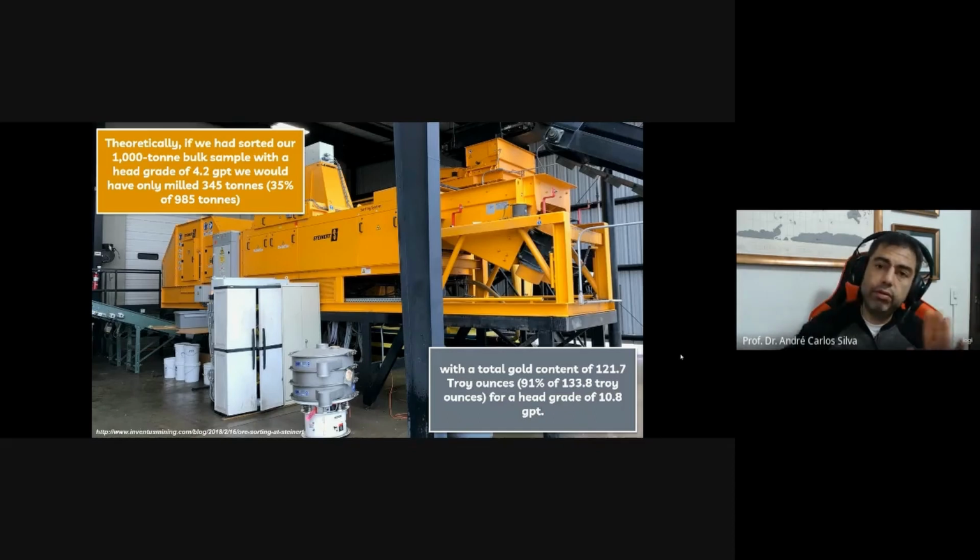Okay, if you consider flotation, again, it's going to be a different chapter. We worked last year with gold samples from the north part of Goiás state, and we got samples with something around 1 GPT on our head samples, and after just one flotation stage, we could reduce the mass to 1/10 of the feed, and the grades went up to 13 GPT. Okay, so always consider that flotation is really powerful. But we can't do flotation on coarse particles like this.